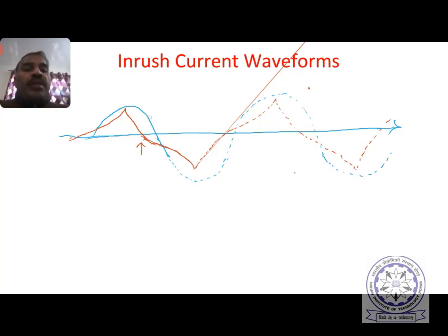Then what will happen? The flux is having a certain magnitude. Will that change? This is actually residual magnetism. When the current becomes 0 also, there will be a certain magnetic flux. Of course, in this graph it is becoming huge, but normally it is not of that level.